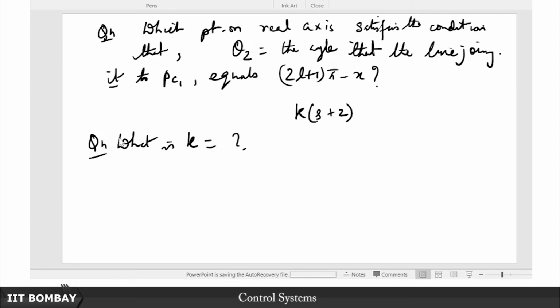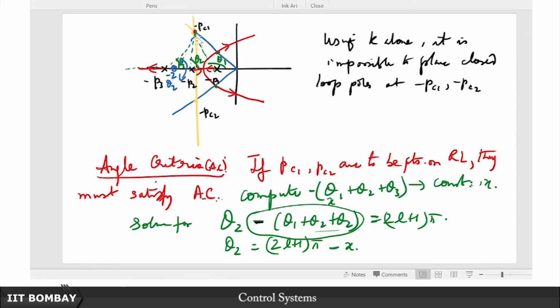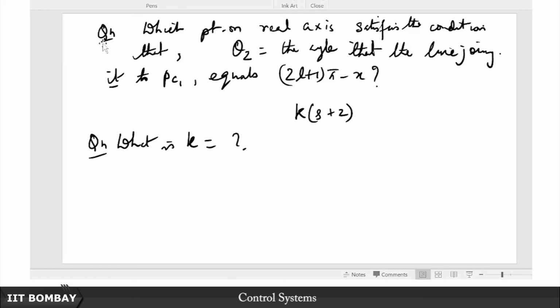In order to evaluate that, we have to just compute the lengths of certain lines. So let us say again I draw this line, this is L3, this line joining this is L1, line joining this is L2, and this new 0 that I have now added, let me just call this L. So now I just measure it off and I say that k is going to be nothing but L1, L2, L3 upon L. It is the same thing that we did here.